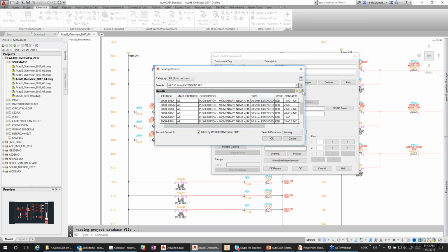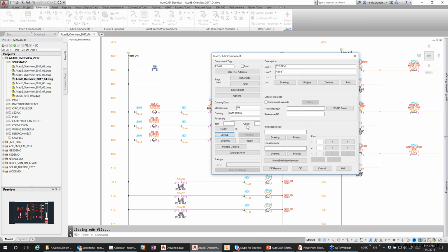You can also use our editing function here to add your own part numbers into the database for your custom type of components. In here we have a freestyle type of search. Think of this as Google inside of this database. I can type in any parts or pieces of the part numbers that I want, and it'll search through that database to find those components. So for example, I'll pick on this component that's been found, pick OK, and then information is added into the dialog box for me. And I could continue throughout the dialog box using various tools to help fill out information.